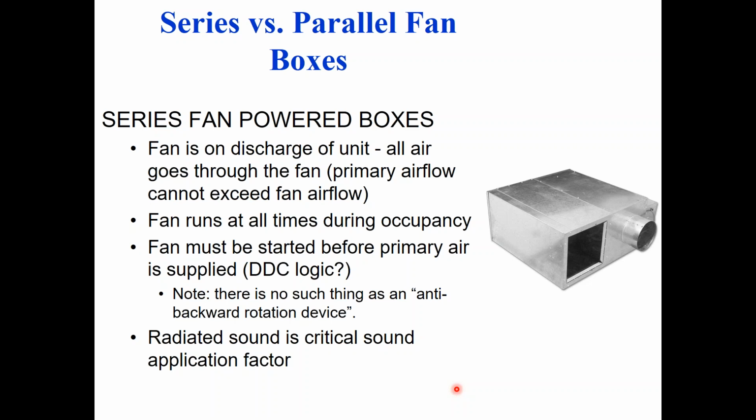The parallel fan of the box will be in parallel with the main air handler's airflow, but this guy's going to be in series. If you look over on the right-hand side here, this round inlet is going to be my 55-degree air from my air handler. This rectangular inlet is my plenum inlet, and then my fan's over here on the discharge side. He's going to pull from both of those openings. So the series fan power box's fan is in series with the main primary airflow fan. That's why we call it series.